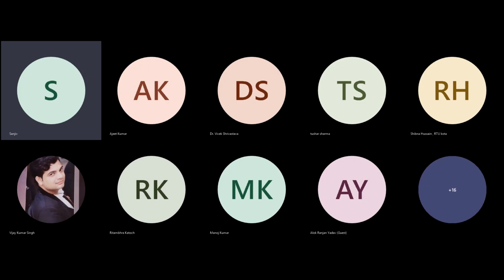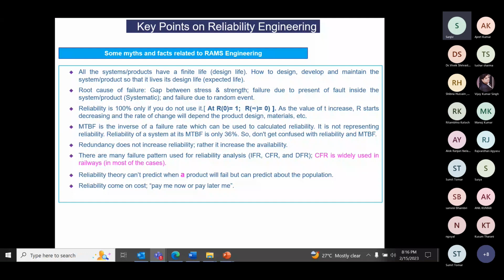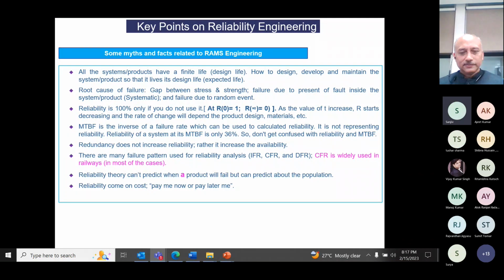At the product or assembly level, redundancy does not increase reliability. I was talking about the system point of view. Just one example: at the system level, suppose you ordered a battery. Instead of one highly reliable battery, somebody gives you two poorly reliable batteries, which serves your purpose, because if one battery fails, I have another power backup.